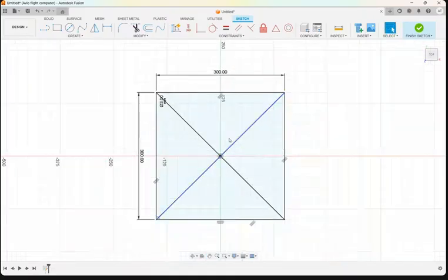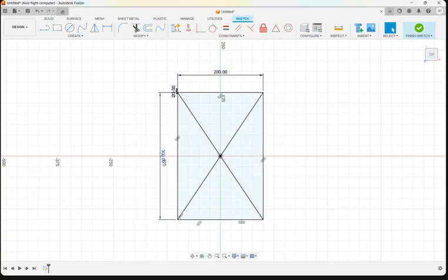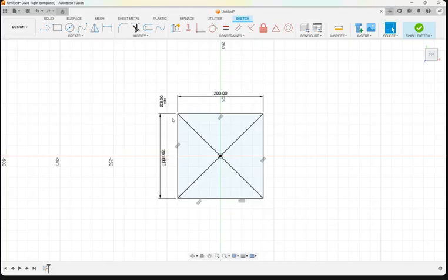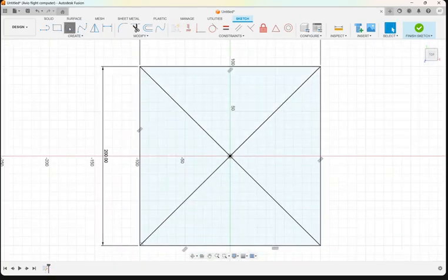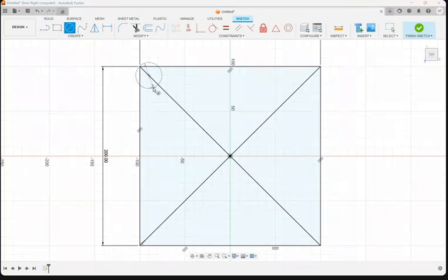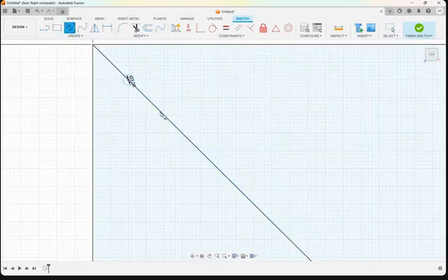Okay, suppose अभी मान लेते हैं मेरे को लग रहा है कि 300 क्रॉस 300 का ड्रोन जो बनेगा वो काफी बड़ा होगा. So what we can do is we can just reiterate with double click, and we can make it 20 centimeter cross 20 centimeter. I can edit it. Okay. And this circle we'll just delete from here. We'll make a new circle over here, 3 mm. So we have a 3 mm hole over here. One more we will do.